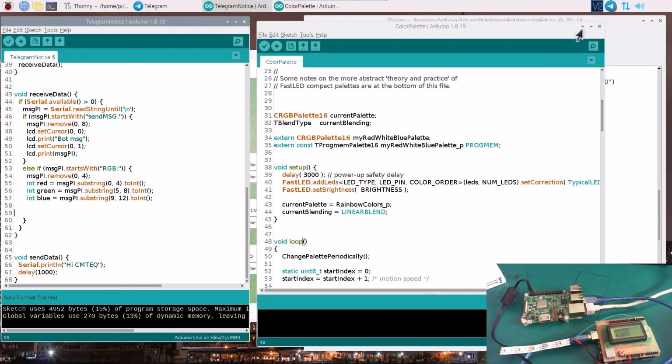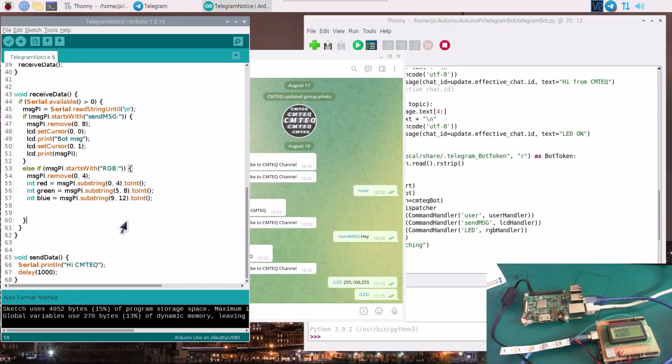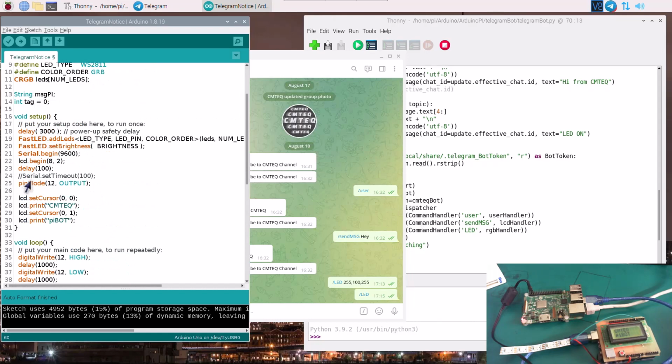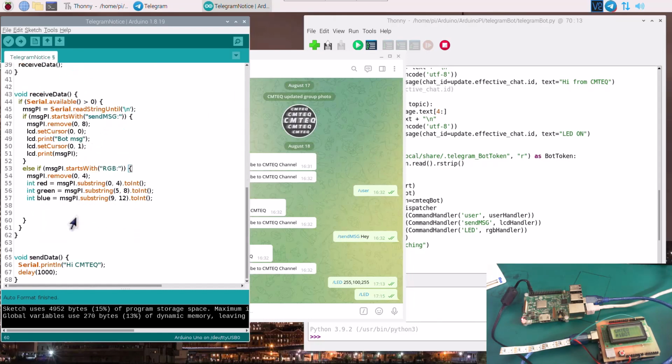Now I'm going to call the RGB function by using the array variable that is defined here. So let's go ahead and call the LEDs array, and we're going to pass the first index, let's say 0. That will be the first LED there. And then we say setRGB. Then we need to pass the parameters here, so that will be red, green, and blue, in small letters, something like this.